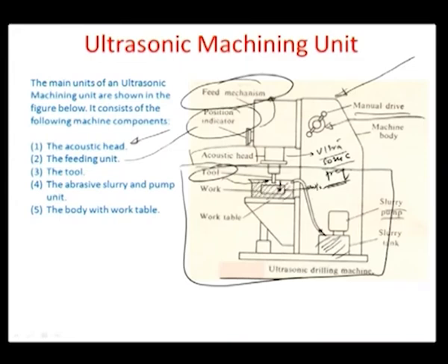So the work is actually immersed inside this cavity, which already comprises a flowing abrasive slurry, and so therefore there is a continuous flow of the slurry into the work zone and taking away of the slurry, thereby meaning that the debris which is generated is also carried away by the viscosity of the material, which would have the abrasive particles in it, okay.